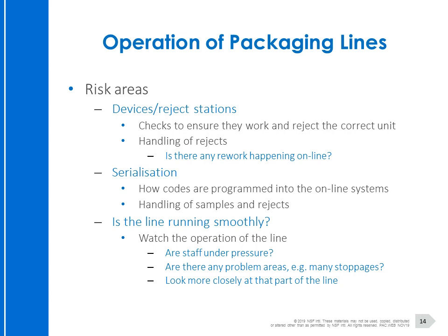And then secondly, what you see a lot on packaging lines is a question mark about the handling of rejects. So what is the control of rejects? If anything goes into the reject bin from any of these devices, are they totally rejected, or is there any sort of rework happening? And thinking about the risks in terms of rework, the potential to possibly introduce problem items into the packaging line, you need to really think about that.